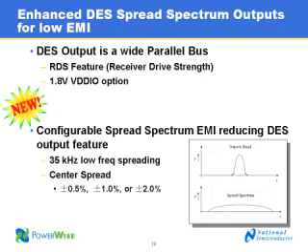So if you're not driving a heavily loaded bus, then certainly run at the minimum levels. And as Alex mentioned, we have the lower VDDIO levels as well to reduce the swing. And with that, you want to make sure that you have a compatible interface to the receiver output. So you'd want to make sure that your logic is running at 1.8 volts on the far end.